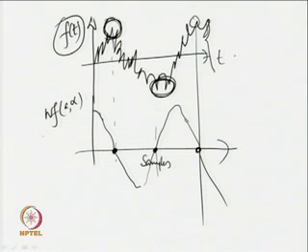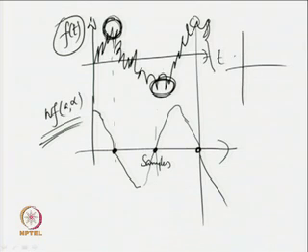So, what is the benefit of getting the 0 crossings? We know that the 0 crossing of this wavelet transform corresponds to the peak of the corrupted signal, meaning the actual signal that is present in the corrupted signal. Okay. So, if the actual signal, let me again give this example, suppose this is the actual signal or the real signal or uncorrupted signal. Now, it will be corrupted like this.